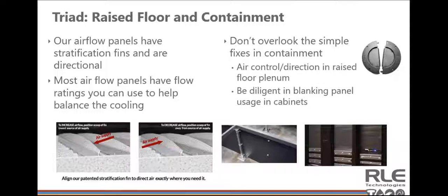Another big key is consistency. Many times I've seen data centers, specifically colos themselves, where you walk in and there were blanking panels used at one time, but they're not now. So you have large gaps, you have large leaks, bypass air all over the place, and that's just causing you to run your cooling systems more frequently or harder to try and maintain that level of cooling.